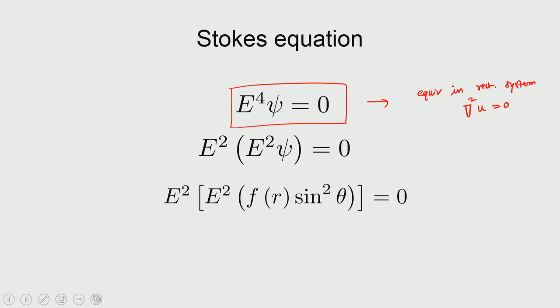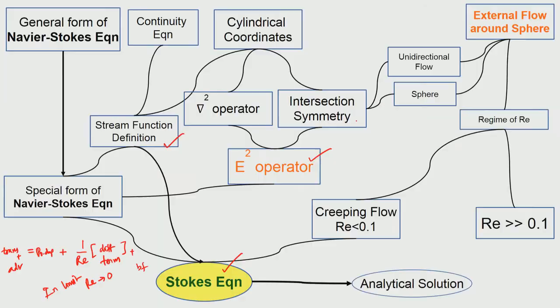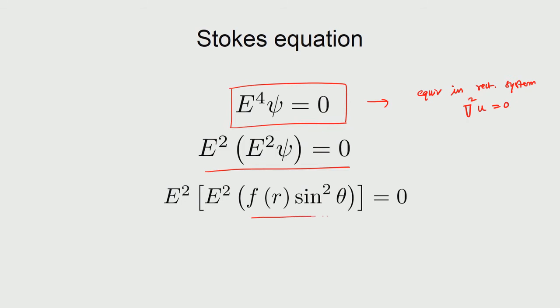So, when you use that, it would then give you a 4th power, and this is how the equation looks. And we have already seen that E4th is nothing but E square acting on itself. So, it is actually nothing but the E square operator coming twice, and we have already seen the form here, E square. Now, the functional form we are proposing the solution to be is here. So, what we see is that when we insert it into the governing equation, it should satisfy.